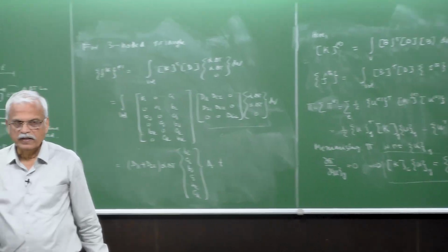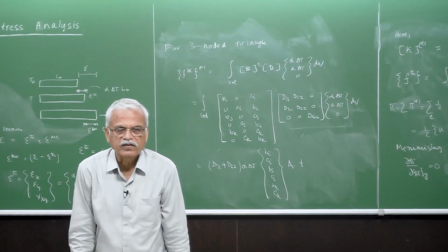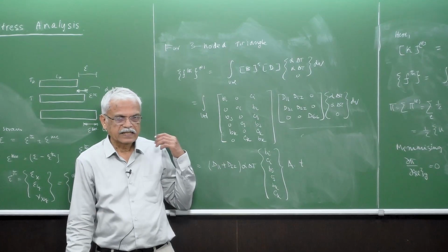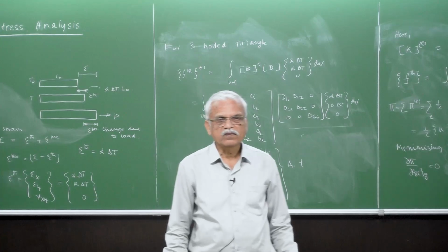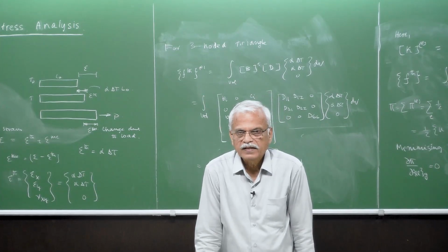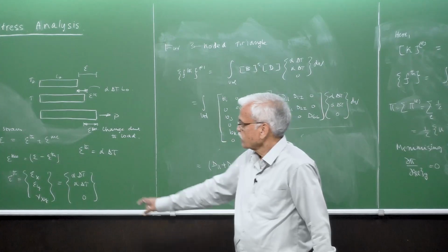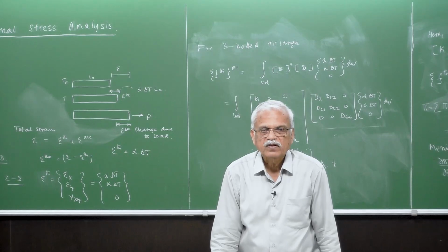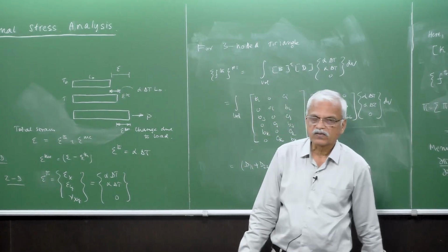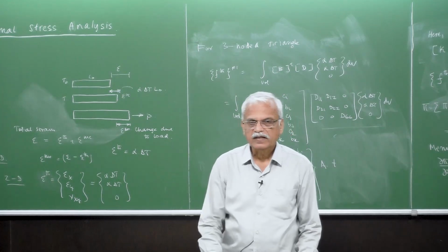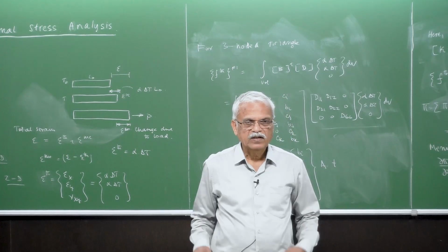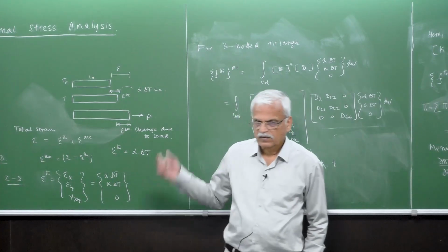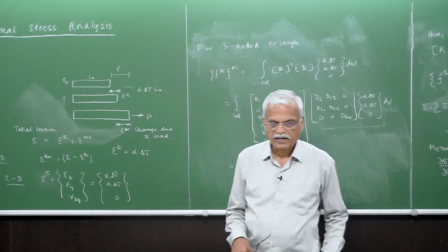And of course, evaluation of the stresses. Finally, if you want to evaluate the stresses within each element, what do we need to take into account? We have to take the stress, if you recall, it was this one. Stress sigma is equal to d times epsilon mechanical, which is the total strain minus the thermal strain. That's where the difference comes, and we'll illustrate it with one example.